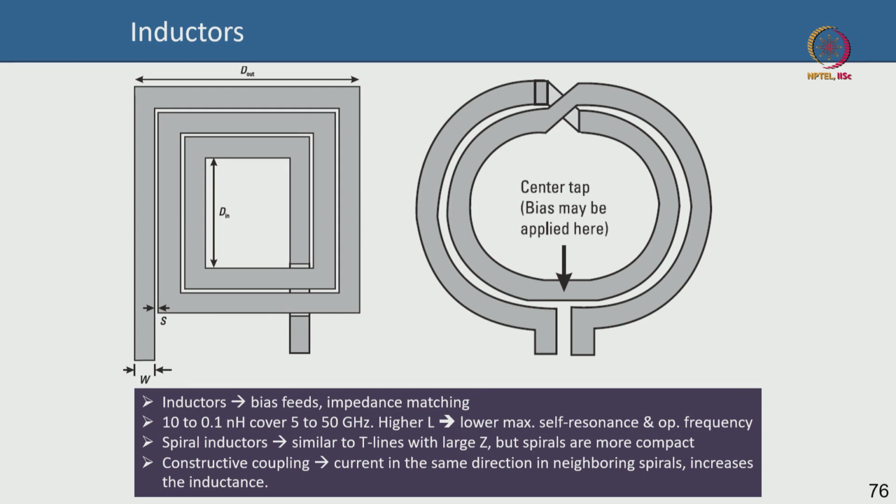You need an on-chip inductor, correct? If you want to talk about passives on the chip, on the wafer, then we are not going to buy an inductor from the market and put it there by integrating. It's just fabricated on the wafer, for instance in an MMIC. You have to fabricate everything on the wafer, on the same die, using the fabrication processes.